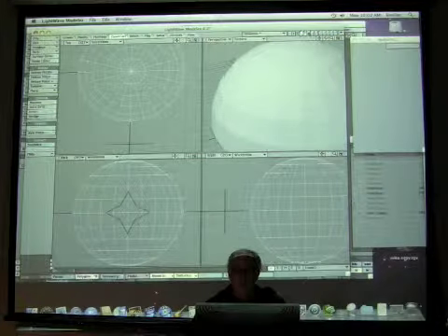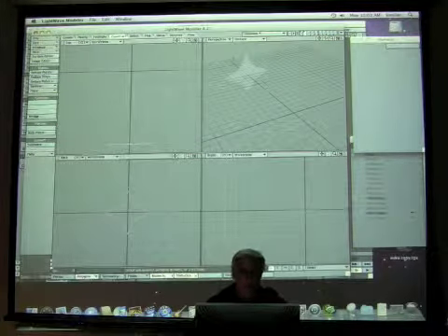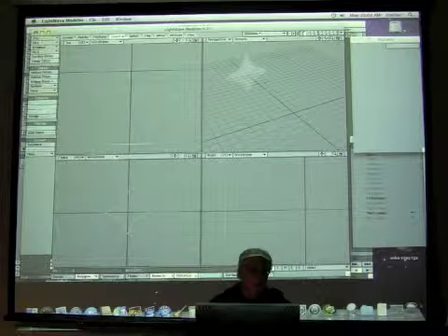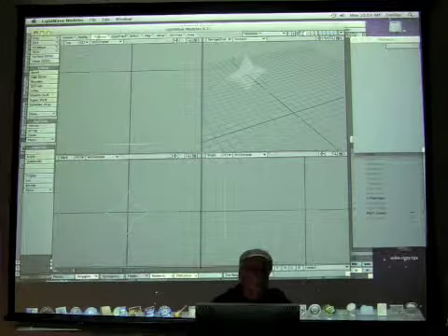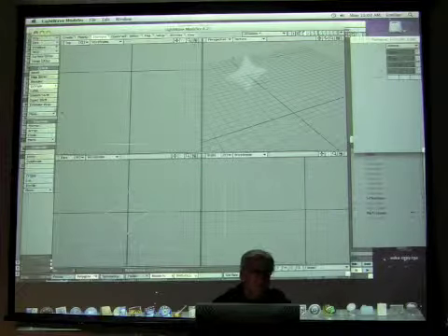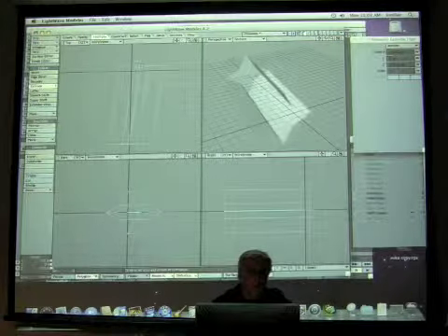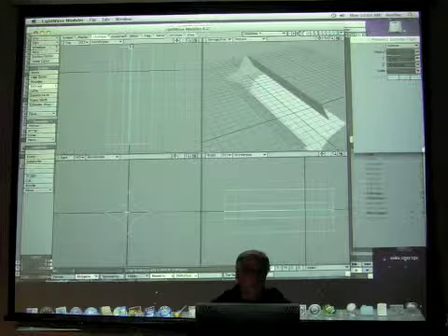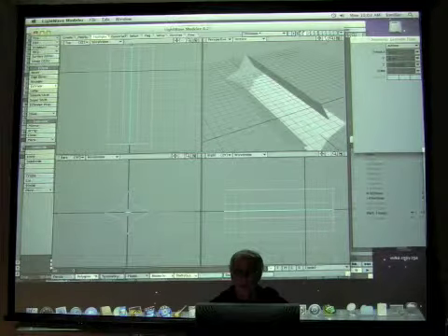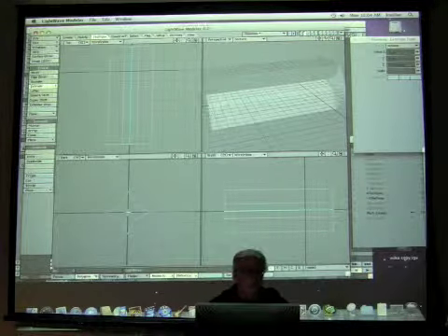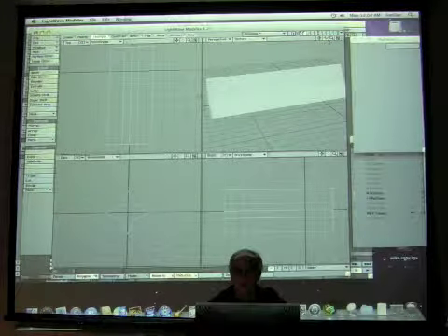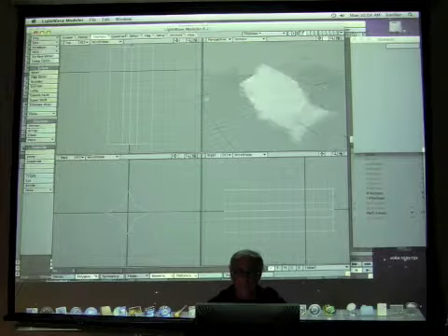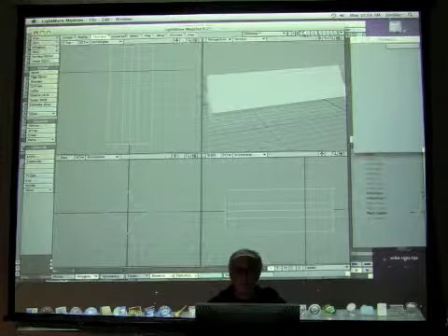And I'm going to switch to the cutter view. In order to get this three-dimensional, again, the quickest way would probably be to select under multiply, select extrude. We can click and drag all the way through here. And again, I've got it facing the wrong way. See how it looks inside out? So I'm going to hit F for flip, and that looks right. Okay, so now I have this extruded piece.